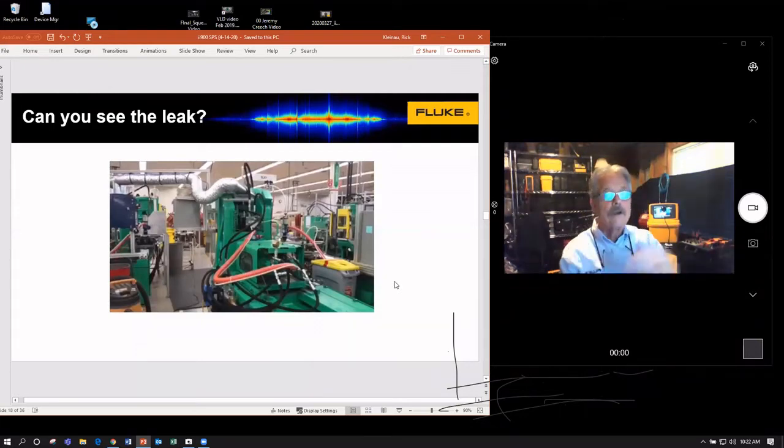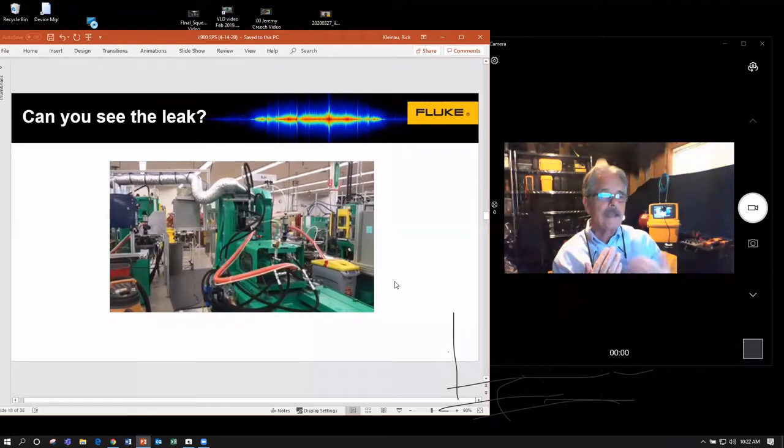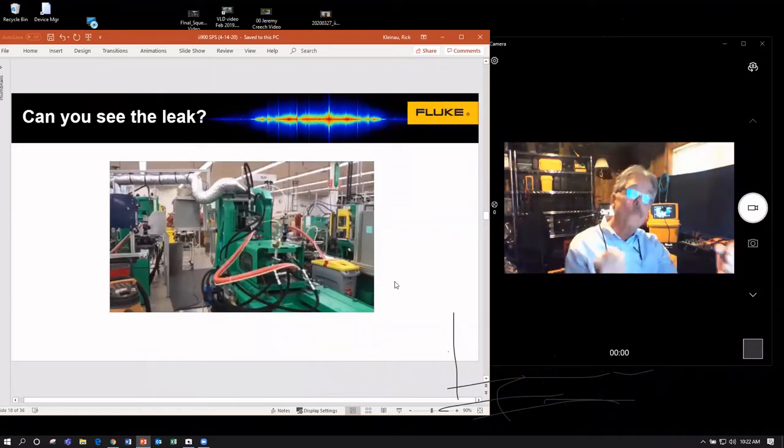What you're really seeing is your body temperature being reflected back off the shiny surfaces in that electrical panel. With the thermal imager, they teach you to move with the imager to look for reflections. That's exactly what happens here with the ii900.